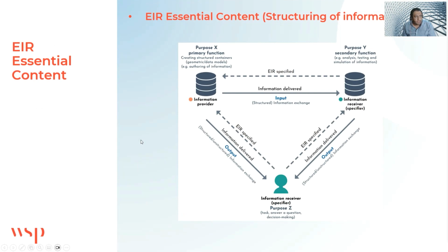Another important aspect for the content of the EIR is the structuring of information. The EIR must specify the structure of information to facilitate open and shareable data across the asset's entire life cycle, ensuring that the data exported from primary authoring processes is suitable for input into secondary processes.